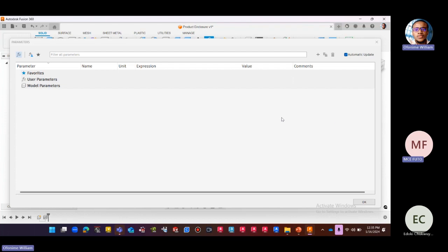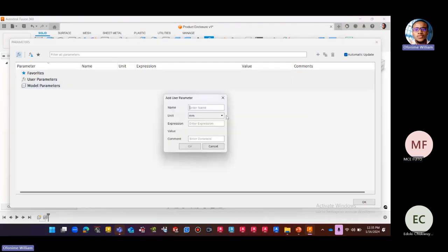All right, so quickly create parameters. The first parameter I'll be creating, I will call this parameter top. You can't keep spaces, but you could use underscore. So I'll just say top, then PCB offset. It's an offset, right? So I'll say top PCB offset. The value we read was 34.599, of course in millimeters, right?